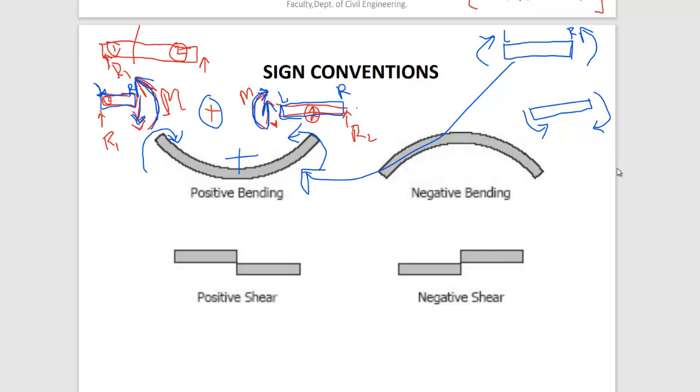Before, you applied the load on the top of the pen, right? Now just apply the load on the bottom of the pen. Can you see the thumb directions and the bending of the pen? It should look like this, right? So if you find the left hand is having anti-clockwise, that time we consider it the negative moment in case of drawing SFD and BMD. And if you find the right side is clockwise, that time we also consider the negative moment.